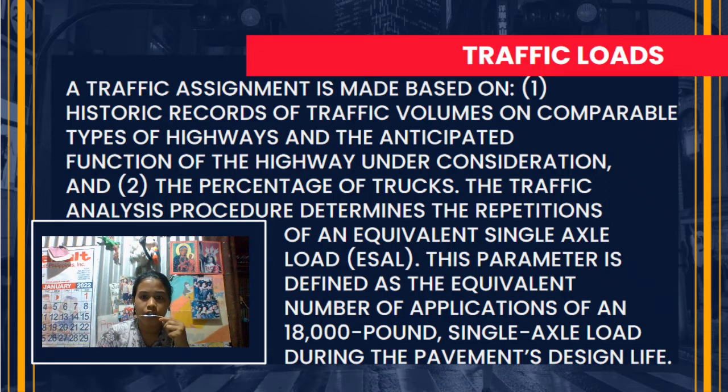The traffic analysis procedure determines the repetition of an equivalent single axle load, or what we call ESAL. This parameter is defined as the equivalent number of applications of an 18,000 pound single axle load during the pavement design life. So equivalent single axle load or ESAL is based on AASHO road test results.